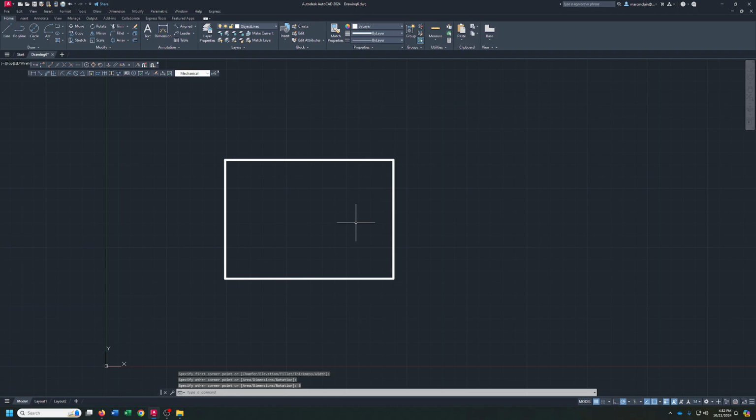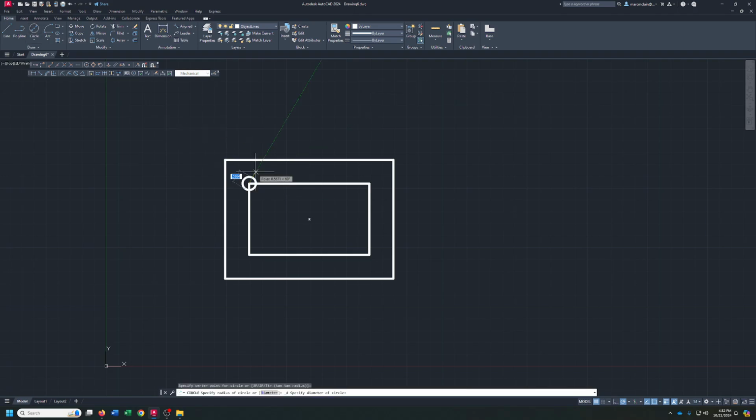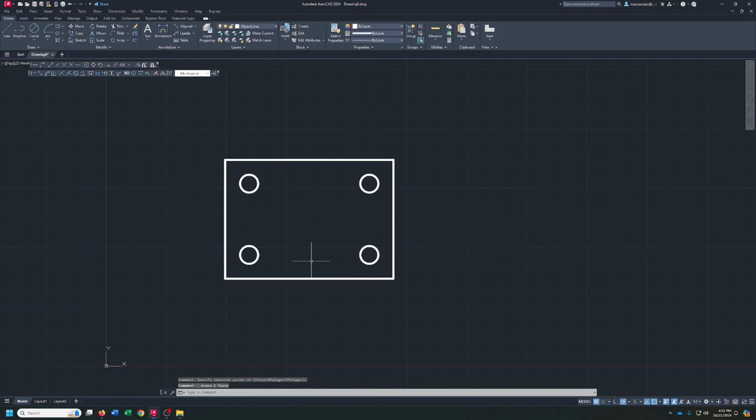And we've got some holes in the sides, so I'm going to offset 1. It's just going to offset as a rectangle, and that's fine. We'll do it like that. Now, I'm going to go ahead and explode this now, so I don't forget to later. And then I'm going to put my diameters here. So this is a diameter of 0.75. And I'm just going to grab that and copy it to each one of the corners. Now I can erase this.